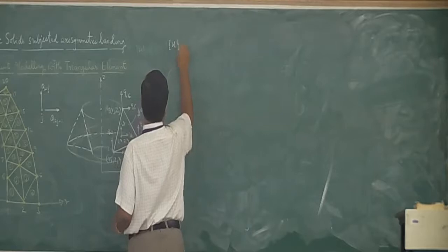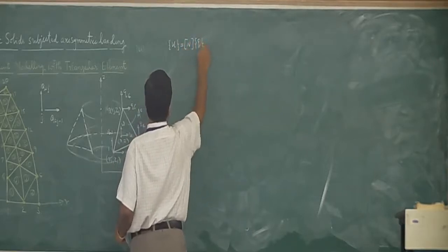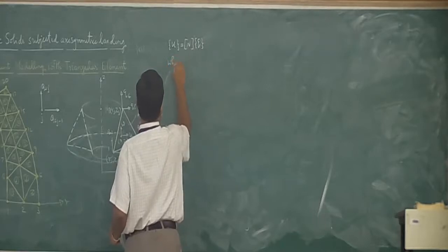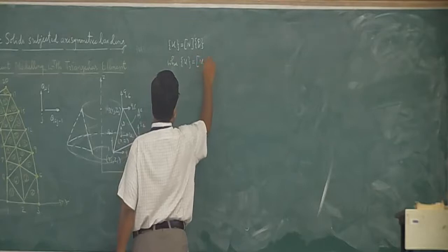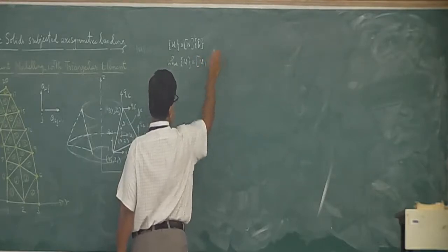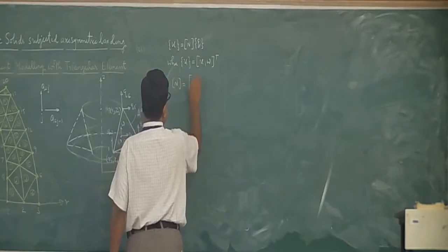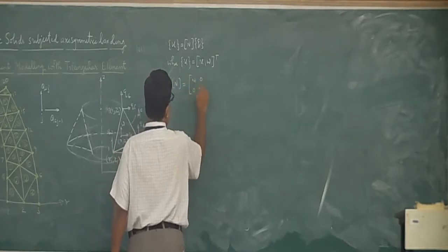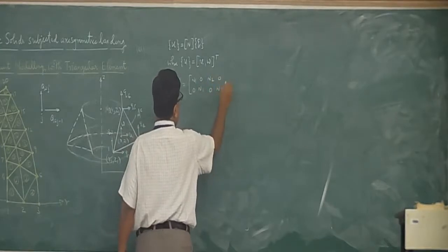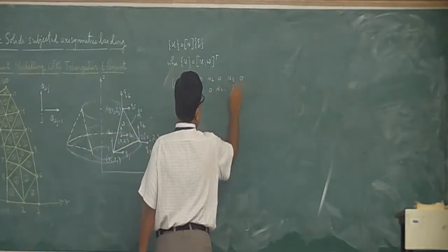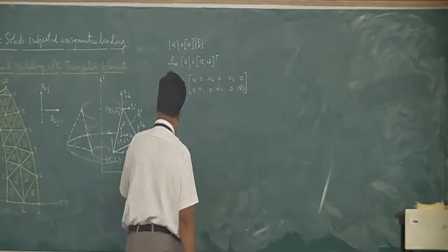We wrote it as u = NQ, where u is now (u, w) in this case, and N was N1 0 N2 0 N3 0 on the first row, and 0 N1 0 N2 0 N3 on the second row. This was the case that you have already studied.